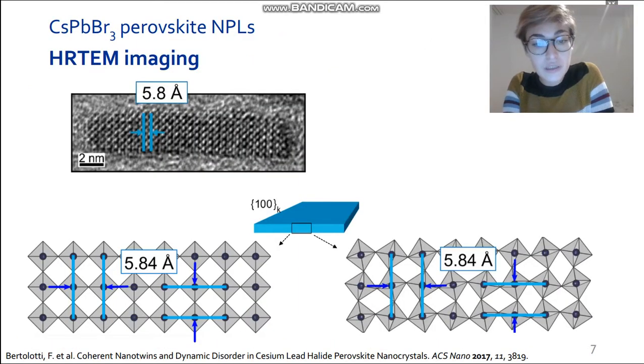Different polymorphs are reported for the cesium-lead bromide perovskite structure, which differ from each other in the bending of lead-bromide-lead angles. The orthorhombic symmetry is characterized by octahedra tilted in equatorial and axial directions with respect to the archetypal cubic structure.